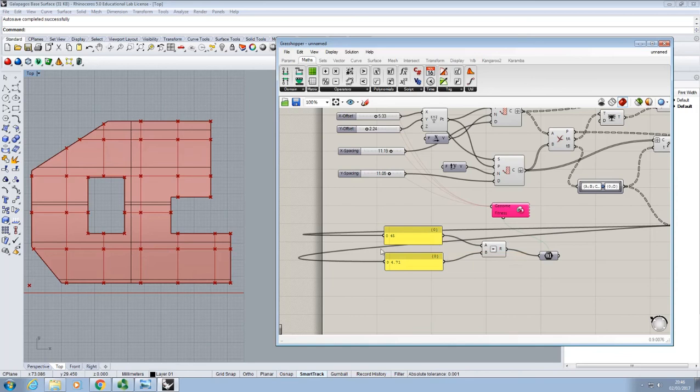So say you wanted to have an area in here which was column free. You could maybe sketch out an area and then check whether any columns were in that zone. And then if there were, then apply to that score a big penalty. So you can say, okay, I want to minimize the score, but if there are any columns within, say, a zone around there, which is my main entryway, then I'll give a big penalty to that score to let it know that that's not a good solution so far as I'm concerned.